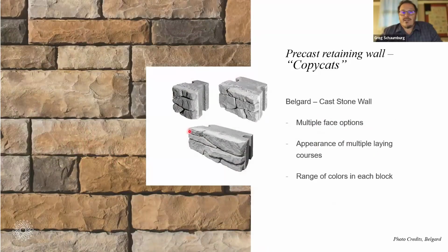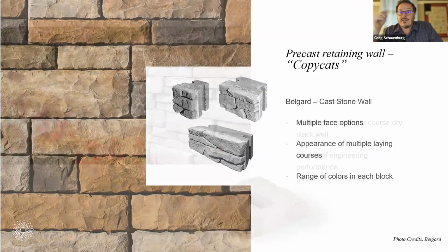That's right. Yeah. So each of these, you can see the key that's in the back here. Each of these is actually a precast face. And a little bit like we talked about in the natural materials, the precast material for paving, there's a face mix that happens on the front, say the front 2 to 3 inches. And then after that, there's a structural mix that's all blended together. And they perform at a really engineered, really predictable level. You can even see that they're trying to do things like this to really break up the linearity and break up the unit size. They'll give you 3 or 4 different sizes, so it doesn't look like you're creating a very regimented piece.